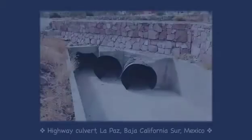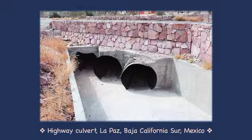The applicability of the rational method is restricted to small catchments. The assumption of constant rainfall in time and space is strictly valid only for small catchments. For small catchments, storm duration usually exceeds the time of concentration. For small catchments, overland flow prevails over streamflow. In practice, the upper limit for a small catchment is in the range 1.3 to 2.5 square kilometers, or 0.5 to 1 square miles.